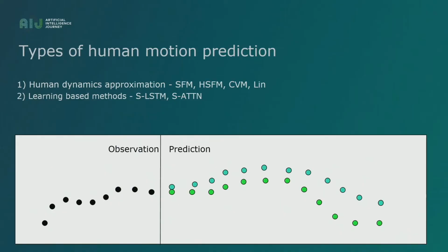By the way, how do we evaluate the result of this sort of forecast? We take into account geometric errors between the forecast and the actual position of a person throughout the entire trajectory. So there is the average displacement error, and the final displacement error is for the final point in the coordinate system.